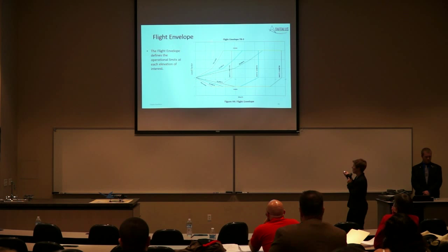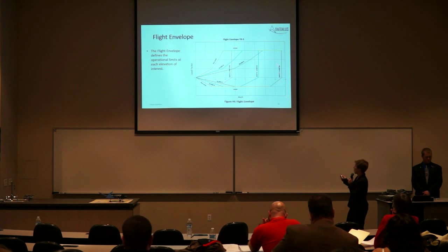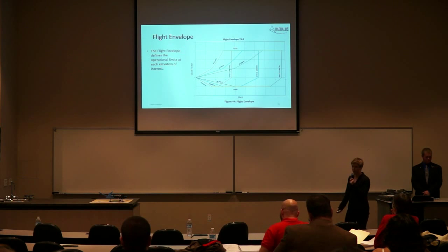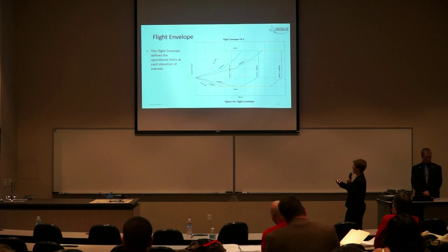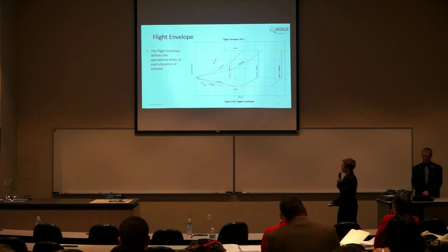It is also shown again for sea level, so during takeoff, you'd be operating in this speed range with very low Gs. And up in this area is an inoperable area because the actual performance limit due to the engines is at 0.5 Mach, which is in this region.